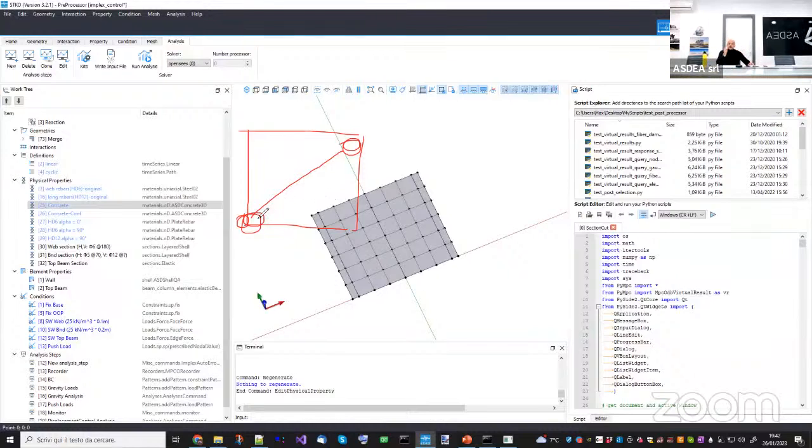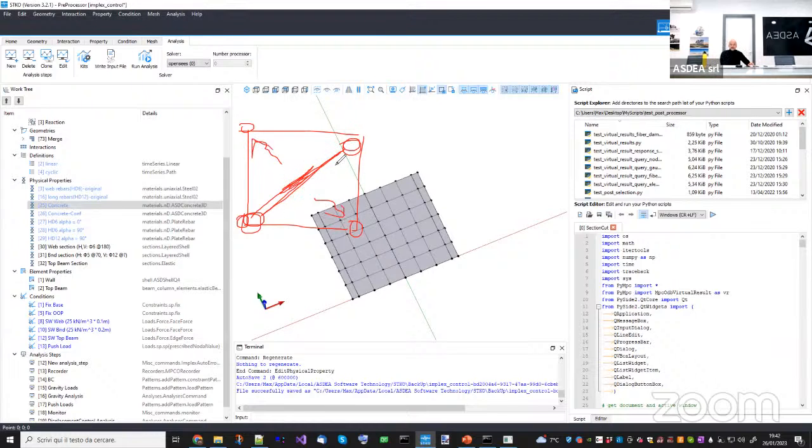As you know, the truss is only aware of the strain in this direction. So they did a modification. They created a truss with 4 nodes, in such a way that they get the direct strain from this truss, and they take the orthogonal deformation. Now, due to the orthogonal deformation, if it is tensile, they change the strength of this truss. So imagine that the strength of this truss starts from a certain FC, and here I have the orthogonal deformation, let's call it epsilon t, and the strength decreases, okay?